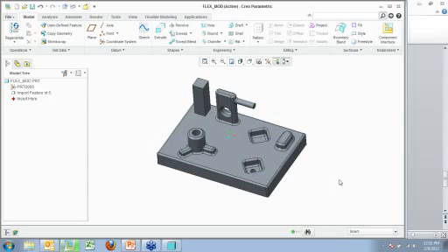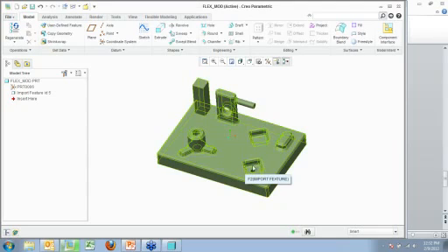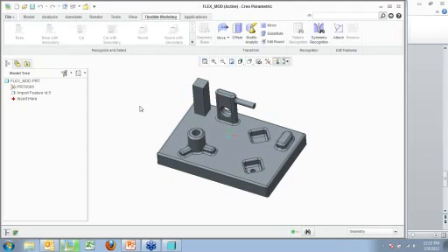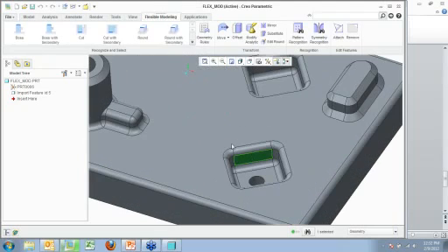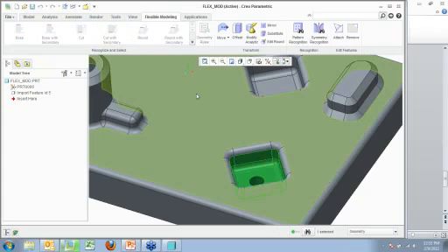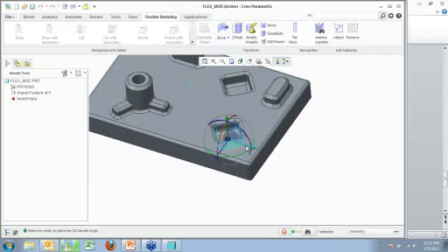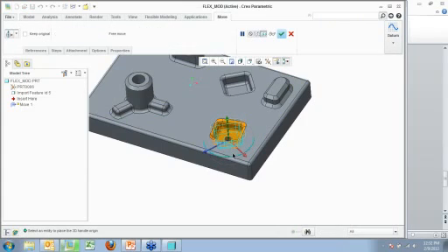This is just geometry. So if I'm doing mold designs or something, and I get something from one of my vendors, and I realize, oh well, this hole's not in quite the right spot. I need to turn this hole by 15 degrees to get the part that I actually want. Then I can come in, select this face. We'll say cut with secondary features. Now I'm going to move this. I can move it using the dragger and actually physically turn this.